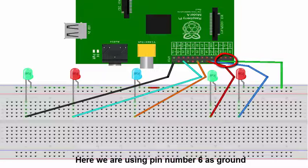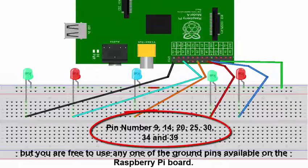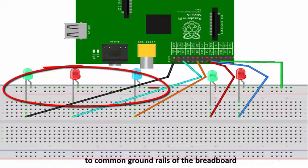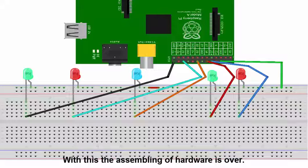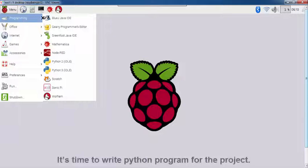Here we are using pin number 6 as ground, but you are free to use any one of the ground pins available on the Raspberry Pi board. You can see that the negative sides of the LEDs are connected to the common ground rails of the breadboard, and the positive sides are connected separately to the GPIO output pins 10, 12, 16, 22 and 26. With this, the assembling of hardware is over, and it's time to write the Python program of the project.